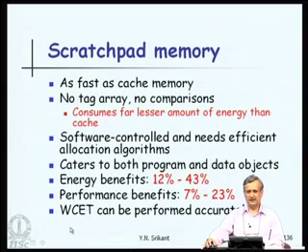There is another advantage. Worst case execution time estimation can be performed very accurately. With a cache, a particular memory access is not known to be either a hit or a miss at the time of compilation. So, the access time is not known, whereas with scratch pad, if we do not have any cache, we know where the data is, either in the scratch pad or in main memory. So, the estimation of time, how much time the program takes, can be performed very accurately.